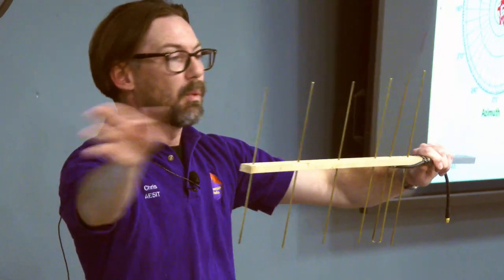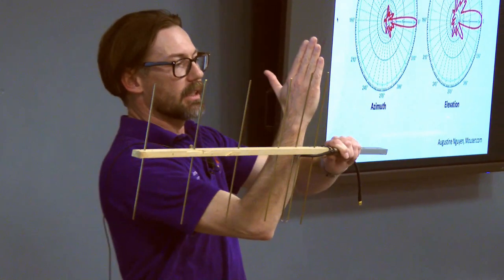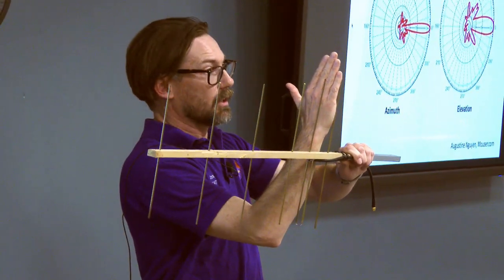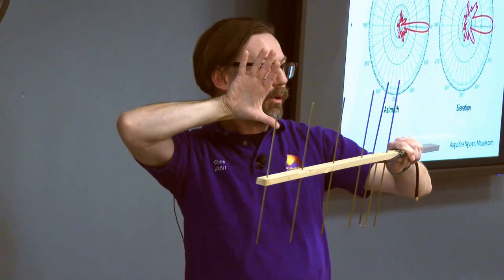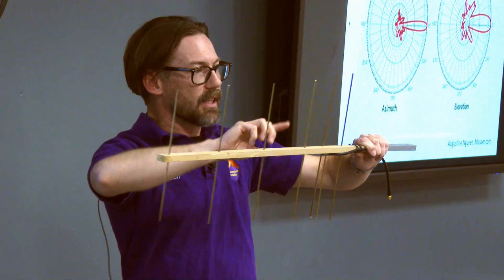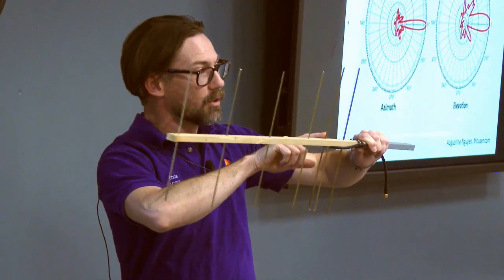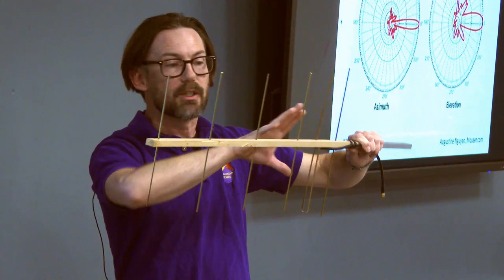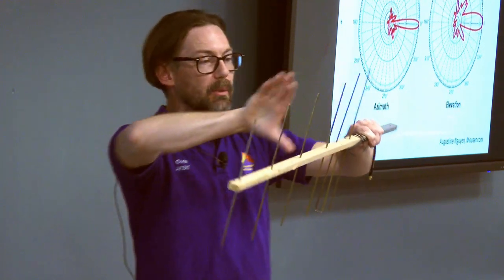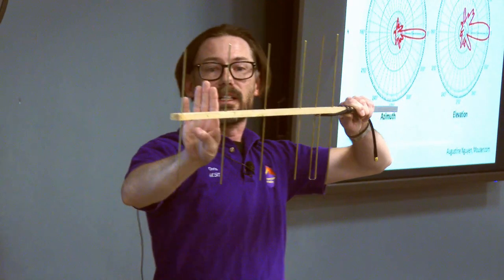But we've thrown all these other wires in here to do what? These will excite sympathetically. This slightly longer one, very close, acts as a reflector. It's like putting a mirror behind a light bulb. And then all these are directors. They will get excited, re-radiate, and those waves will all interact with the original radiation from the dipole in such a way that it focuses. So we have a reflector, like a mirror behind a light bulb, and a series of lenses.